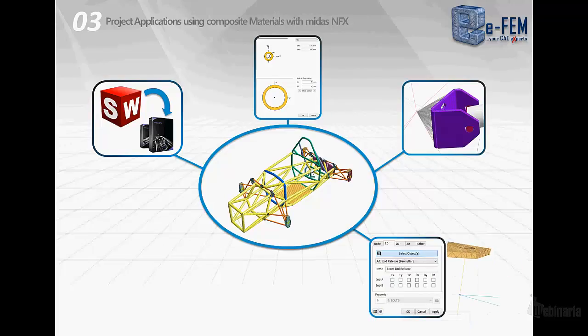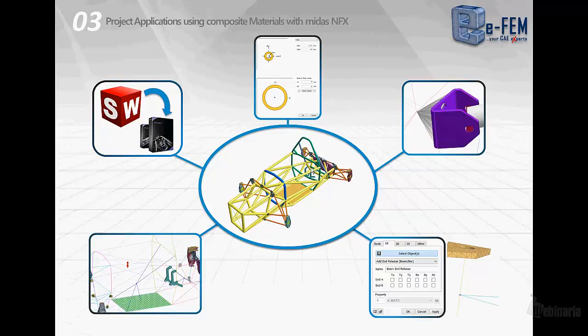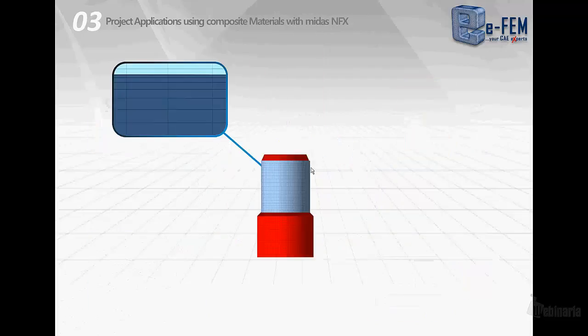Because the model also represents the suspension triangles, it is really important to define the correct nodal releases in order to describe well the kinematics of the frame. Then the model has been completed with loads and boundary conditions.